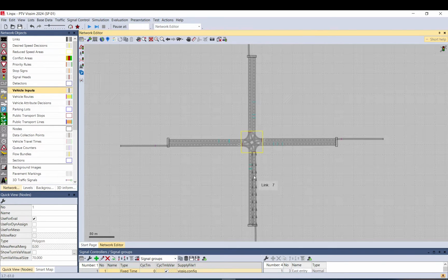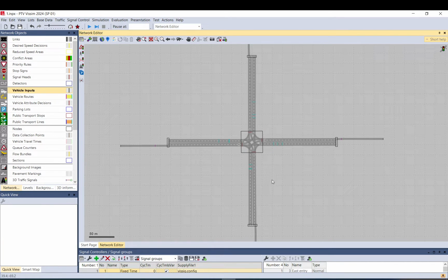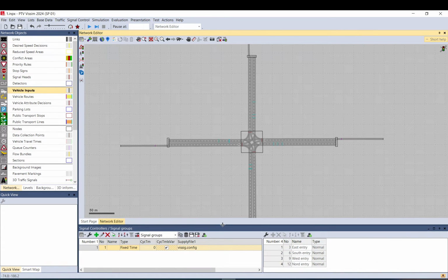Or we can actually use cautious as well and not normal, so the difference will be more significant. What we do is first set up the driving behaviors, then set up the vehicle types, vehicle compositions, assign the traffic, and check the node evaluation, how it goes. And we put a little chart probably to just show what's going on, to visualize the outputs.